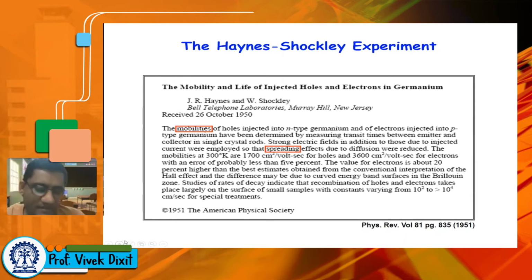By Hall measurement, we can measure the conductivity. So we get the conductivity of the piece of semiconductor, which is used because we are applying an electric field there, right? So it is basically controlled by the majority carriers. Then we apply the magnetic field. This voltage is developed, and that is again controlled by the majority carriers. So we get the mobility of the majority carrier.